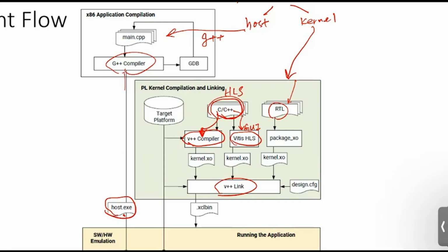Okay, so when you're doing initial development, you're doing a lot of debugging and performance tuning, so it's better that you develop the HLS in Vitis HLS. It provides a lot of analyzers too, and then you can evaluate the resource, performance, everything. So when it's done, you can convert to this path, with the proper pragma and the source code developed, then you go through this flow.